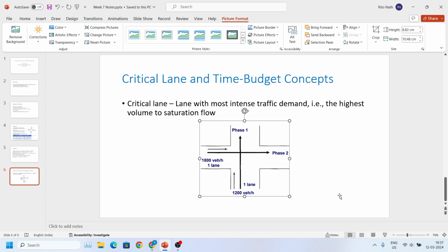So in that example, there were some recommendations that northbound movement should have 2 lanes and eastbound movement should have 3 lanes and so on. I'm not going into that example again, but that was the gist of that problem, and this is relevant in this context: additional lanes in both directions can provide shorter cycle lengths and so on. So this has direct relations with the signal timing design that we'll be doing.